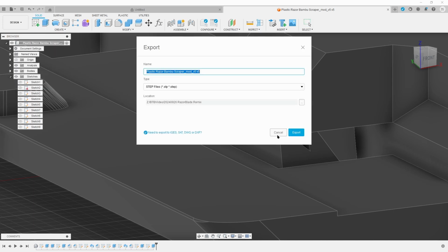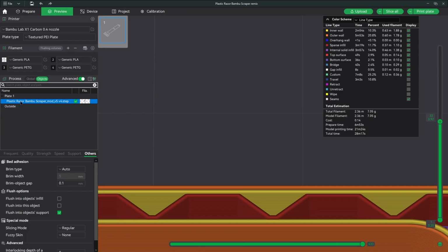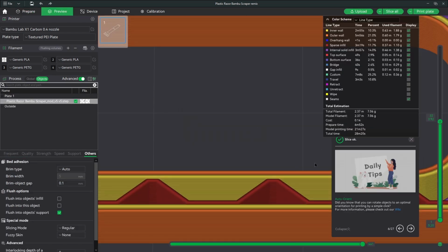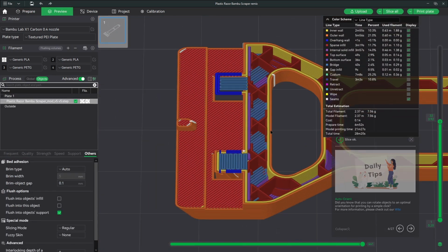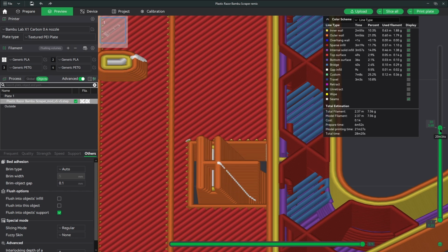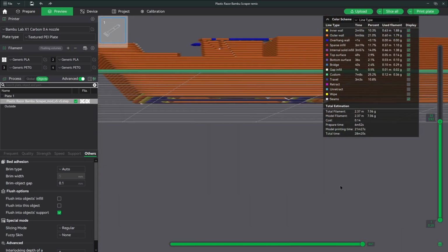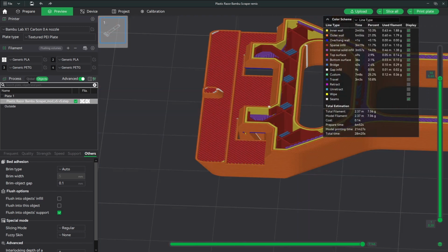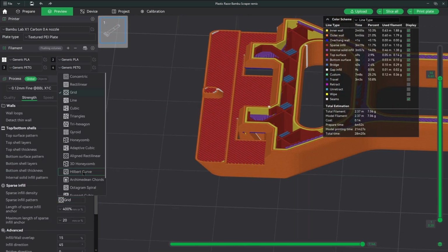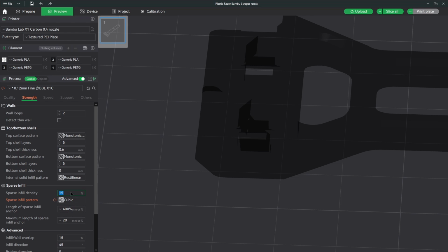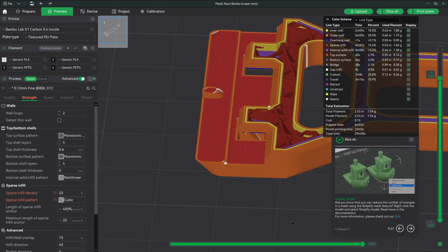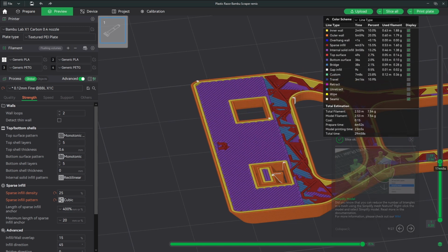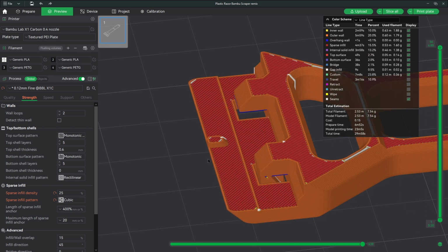So there we go. We have a piece of geometry where the interface with the upper levels is very, very narrow. It's one width of extrusion. And this double T shape will support the geometry that is created. So I make some adjustments to the infill. I flip over to cubic, which generally I prefer, at 25%, and I'm looking through all the layers to see how it looks, where it's supported, and where features grow. I like the look of it.